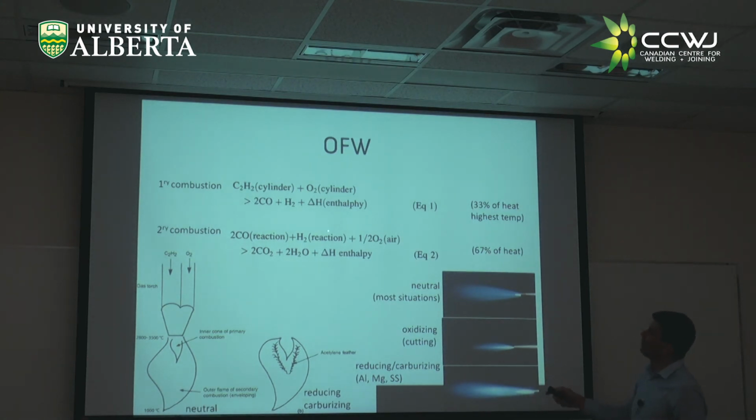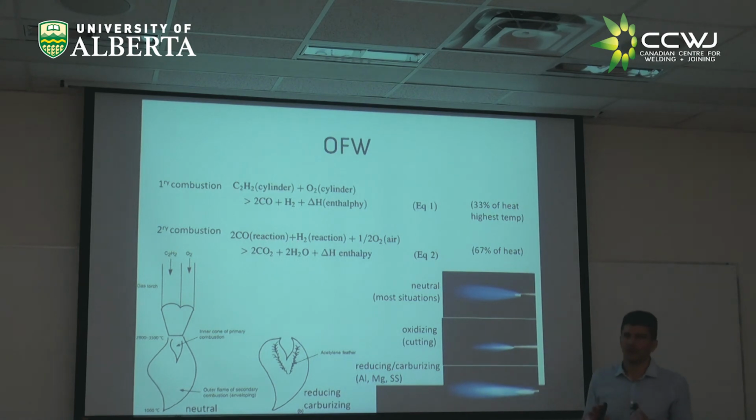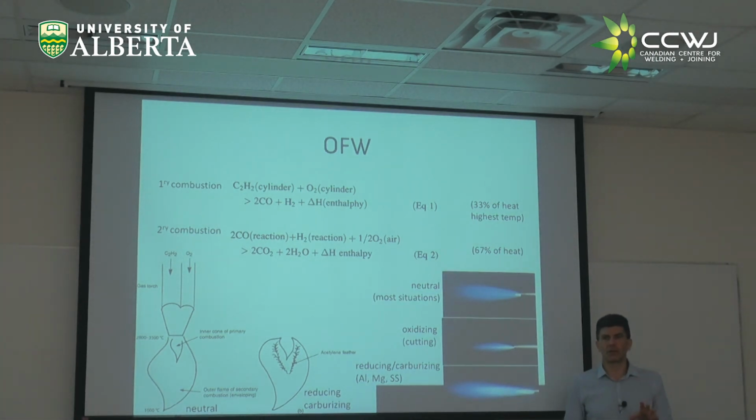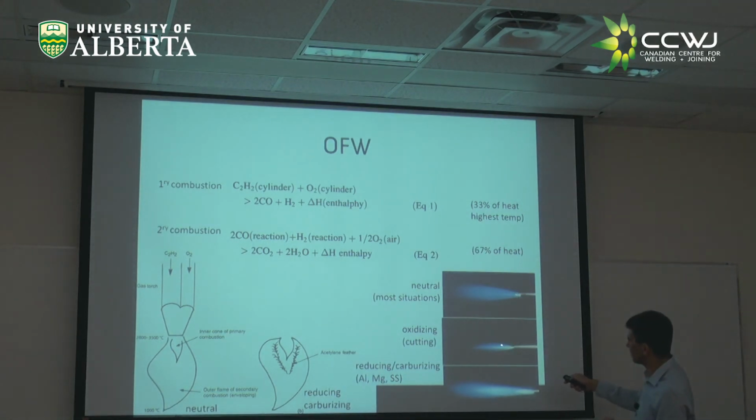And what first happens is a partial combustion in which the carbon loses the hydrogen, right, and partially oxidizes and releases energy, right, and hydrogen. Now, about 1/3 of the heat of the combustion comes from this first stage of combustion. However, because that heat of combustion happens at the tip of the flame, that is very hot, right? And you see this inner core that is hot.